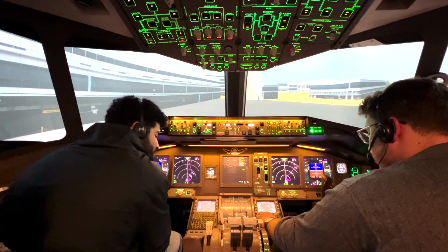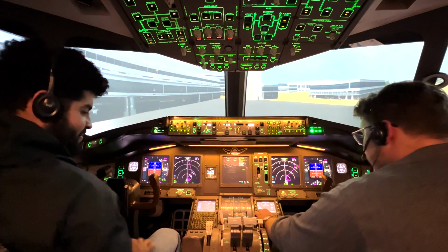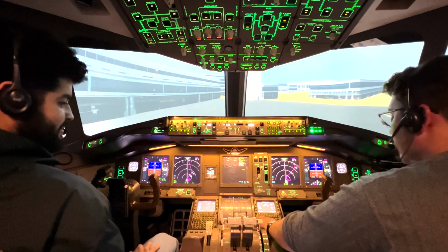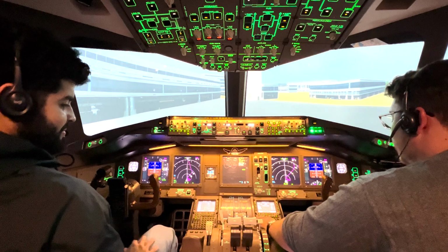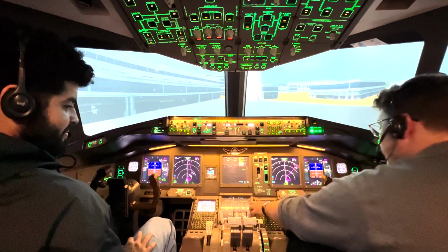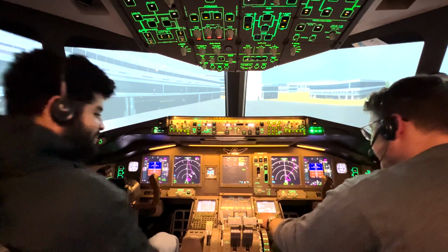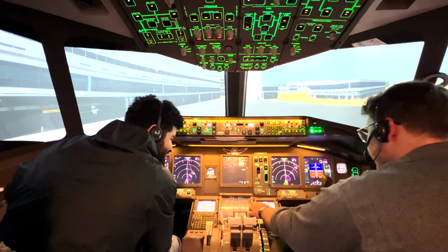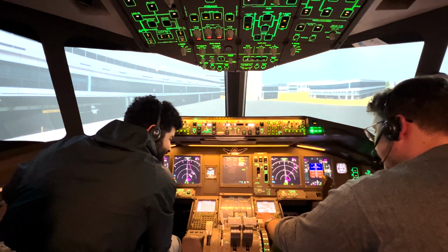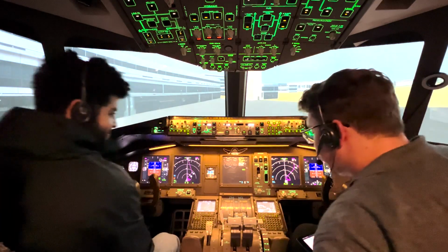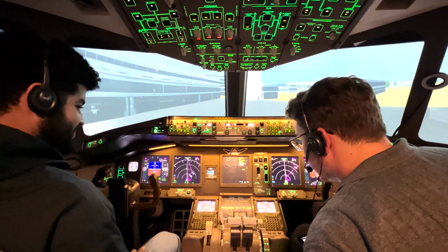And there's our center of gravity. Thrust limit, it's outside air temperature is 12 degrees. We are in Austria. It is September. So I'm actually going to say it's 8 degrees outside. And that should limit our takeoff thrust. We're doing a flaps 5 takeoff. And our center of gravity is 20.3%, which gives us a trim level of 5.75. So we'll make sure that 5.75 is set on the trim.